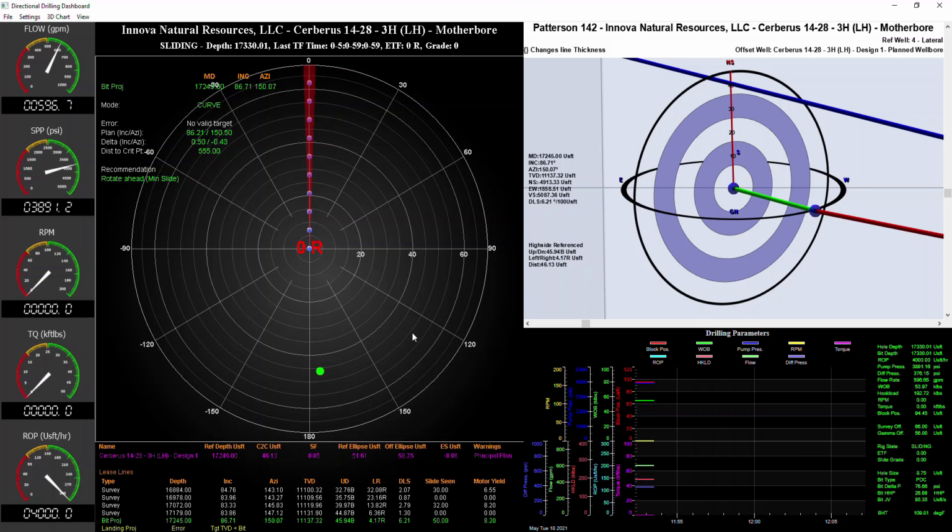So within this dashboard we have got down the left hand side some gauges. Now these will take any WITS data that we have been receiving and they will display them here for us, so we can clearly see some of our input feeds. And these gauges are all adjustable, so if you didn't want to have RPM but instead you wanted to have weight on bit here, for example, you could make an adjustment here.